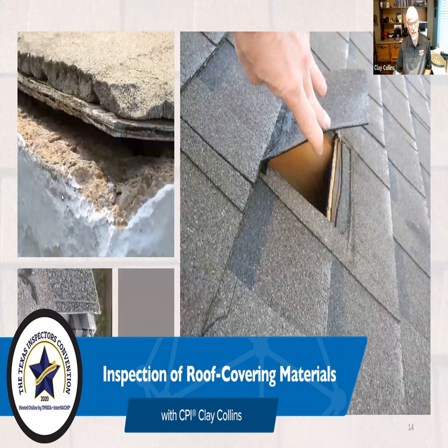And then what about the roofs that can be damaged? Obviously, clay and concrete tile is going to be breakable. Let's not spend much more time on that. I think we all know that those tiles break and we shouldn't get on them. Even though you have to walk on them to install them, we as inspectors would be held accountable, I think, if we did break the tile. So just stay off of it.